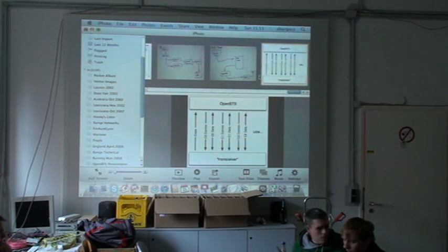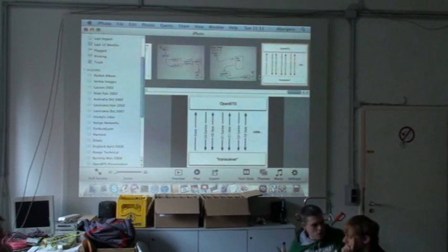I did some tests on receiving, and I found that just analyzing the power of the channel before doing the correlation, with a very low threshold so that you do get a lot of false positives, saves some computational power, not trying to correlate noise where there's no power.